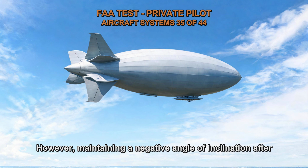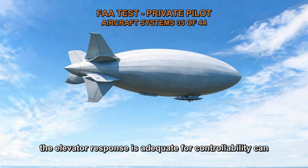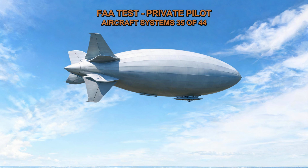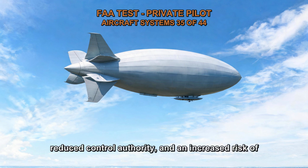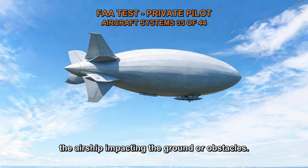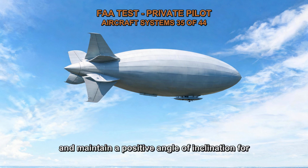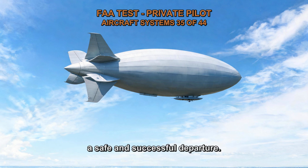However, maintaining a negative angle of inclination after the elevator response is adequate for controllability can lead to an unstable and unsafe situation. It can result in a loss of lift, reduced control authority, and an increased risk of the airship impacting the ground or obstacles. It is essential to follow proper takeoff procedures and maintain a positive angle of inclination for a safe and successful departure.